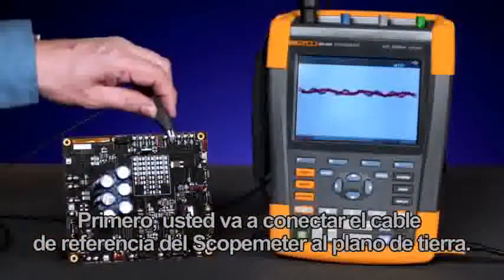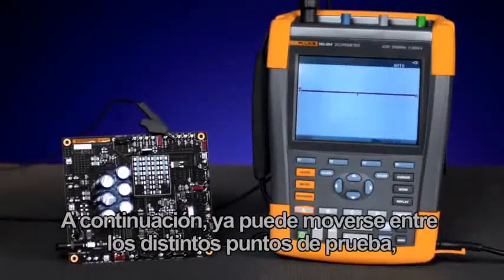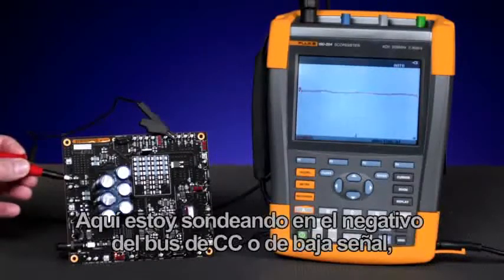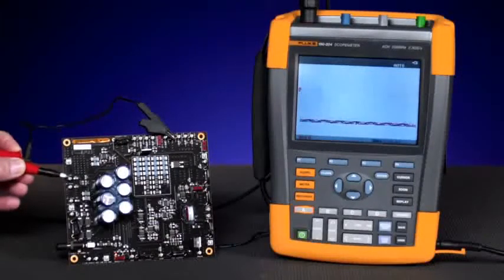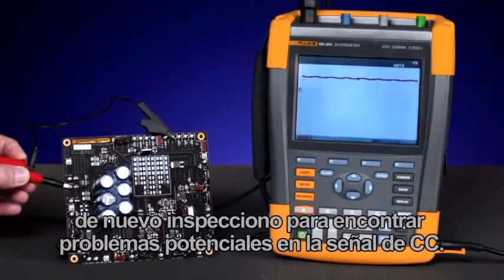First, you're going to connect the scope meter reference lead to the ground plane. Then you can move from test point to test point, looking at each of the critical test points for signs of failure. Here, I'm probing on the DC bus negative or low signal, looking for any signs of distortion or dropout of the signal. Moving to the DC high signal, again, inspecting for any potential problems on the DC signal.